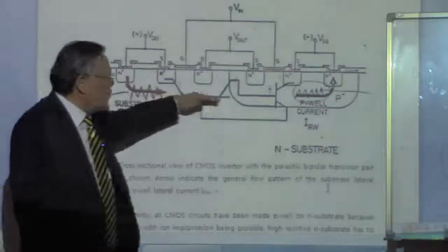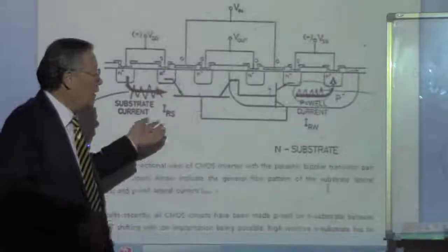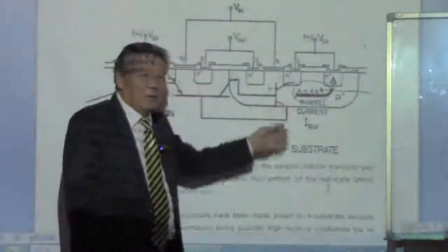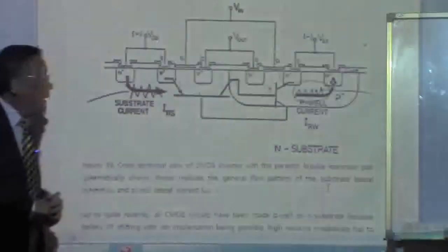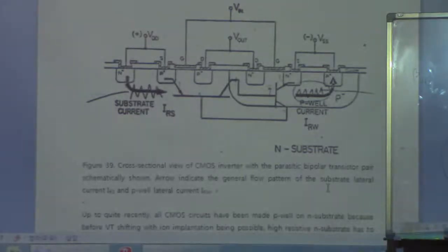And the lateral bipolar transistor inherently has a lower value of beta than that of the vertical transistor. So lifetime control to decrease the latch-up by damaging the silicon wafer is not a good way to prevent latch-up. Okay? It cannot be a good way, but that's one way we can think of.